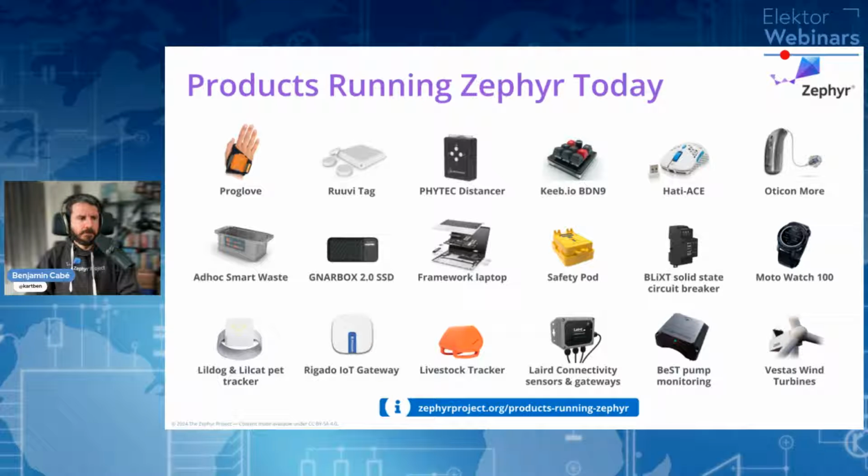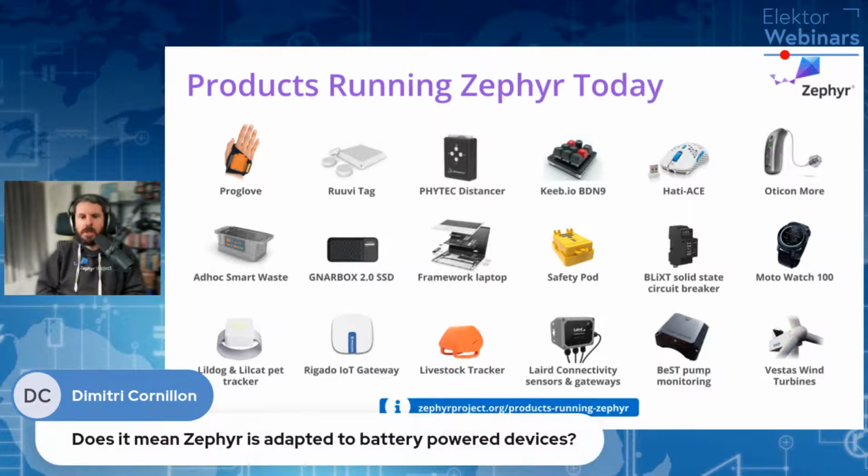I see a quick question in the chat: does it mean that Zephyr is adapted to battery-powered devices? Yes, very much so. You can think of just a few microamps of power consumption for your application when it's doing nothing, which is usually most of the time, and that's where having an RTOS is really interesting.